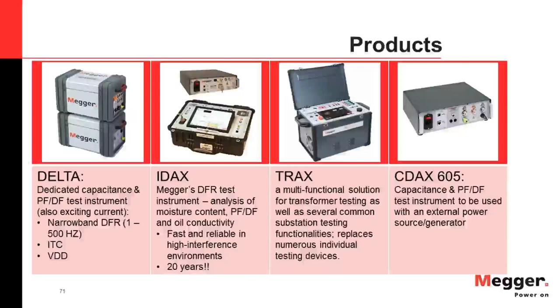On the flip side, if this thing is just drained because I've been in the middle of processing the transformer, and I think it's dry, but I want to do a quick check on it, break the vacuum, and then do a power factor measurement to see if in fact I'm right.